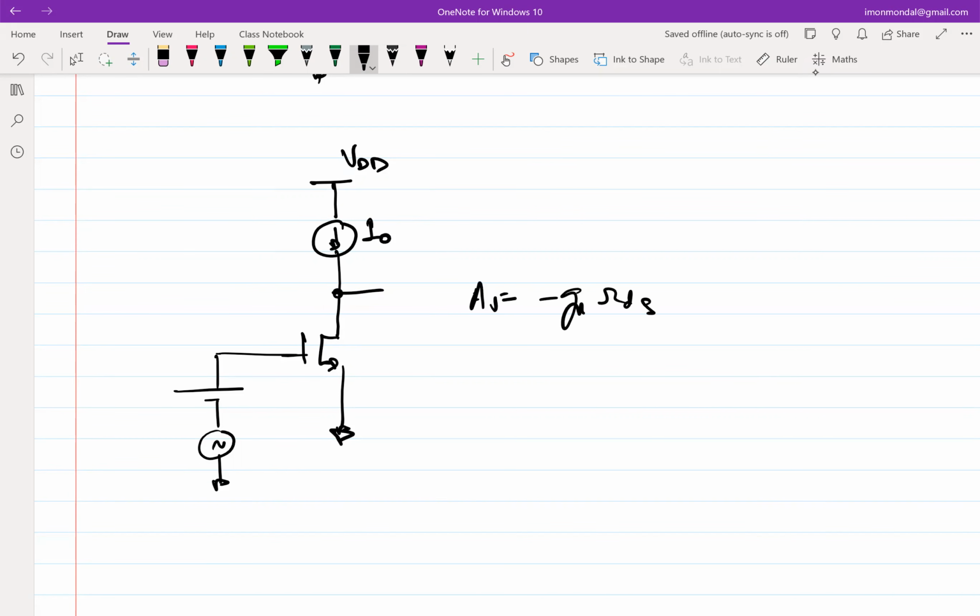Now the question boils down to how do I implement this current source, right? So in our case, we are essentially constrained to the use of one current source, and we can use as many MOSFETs as we want. So that's not a problem. So we saw how to replace this current source in the tail transistor of my diff pair. Now what I'm trying to get at here is how do I replace this current source at the drain side of this transistor, right?